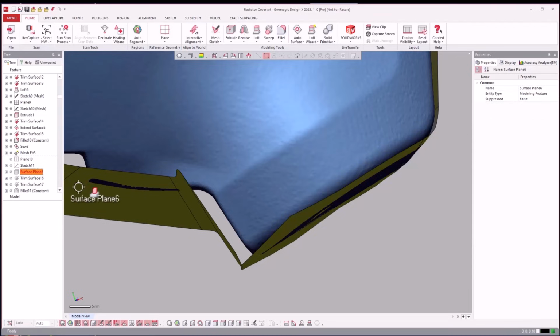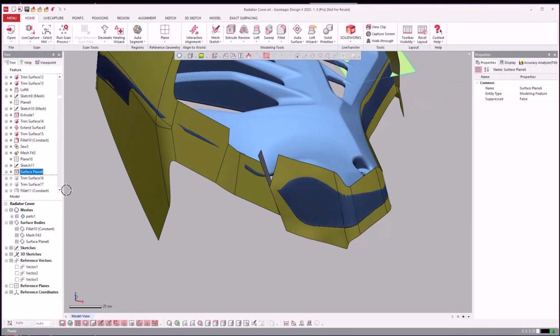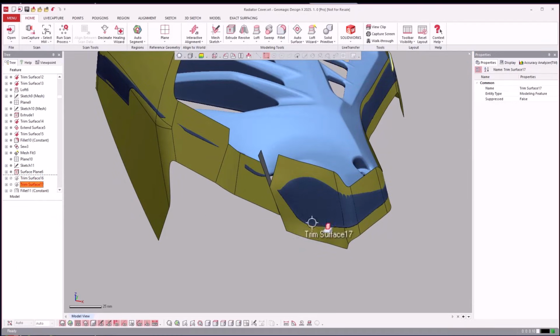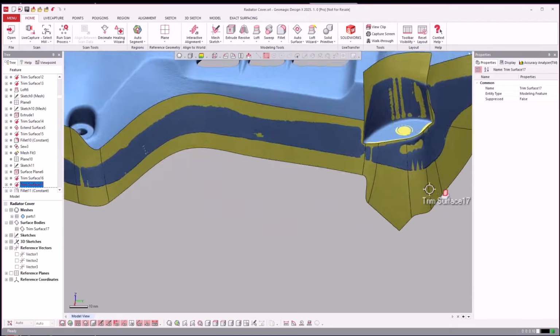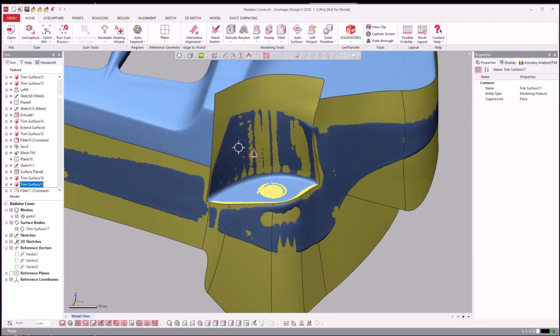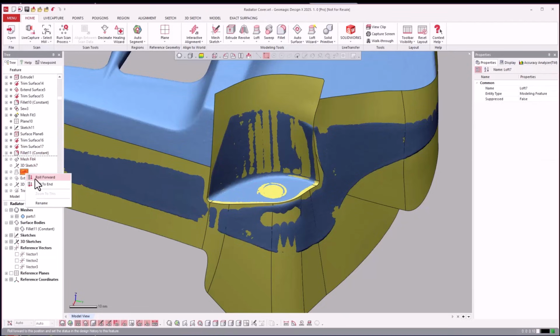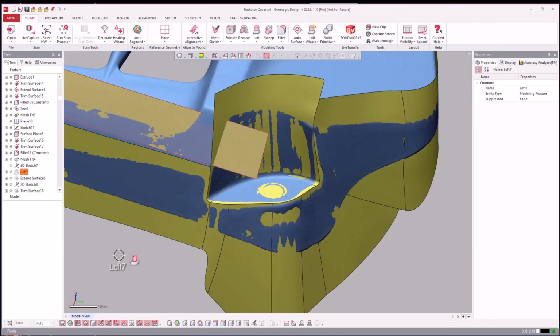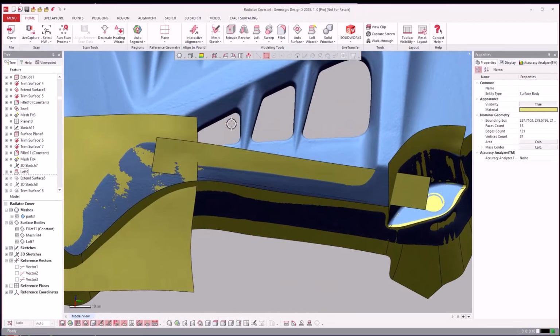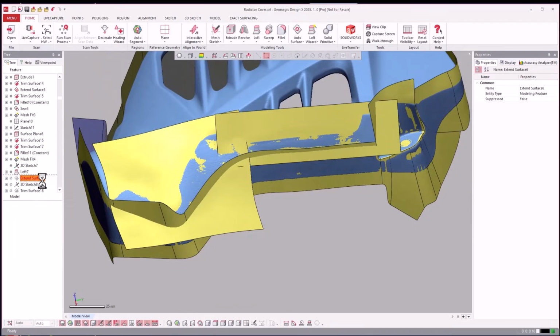But now we can jump forward, and you see that we're wrapping all the way around. Trim, trim, trim. And now we're over there where we just did a notch trim out of there. So we trimmed those together. We did a surface, trim them together, and then trim it away from our boundary. And then we'll jump forward here. So now we're going to start creeping up this side here. So we fit those two together, extend them out.